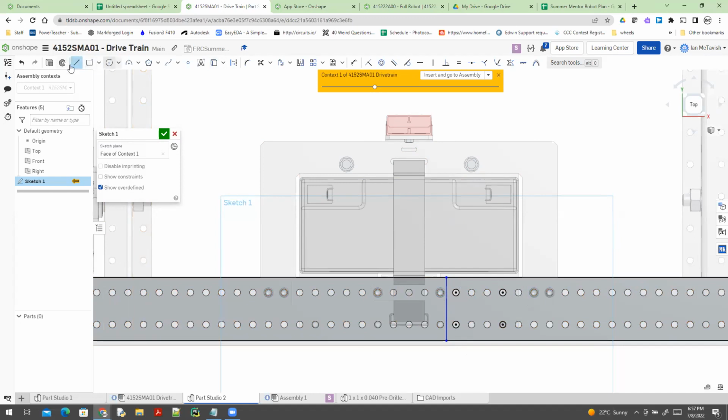If you haven't done creating a part, this is going to be very complex, but all I'm doing is creating a bunch of lines, and you'll notice that I've got little icons on the screen. That line shows up in orange, and those are constraints. That constraint tells me that this line is going to be a vertical line. The other constraint is coincident, which means it's touching that line. And then there's my dimension tool, and I can specify how far apart these things are. I'm just going to go 1/4 of an inch.